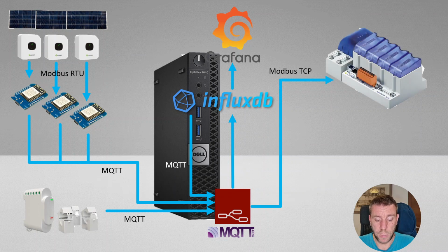And then once this is all in MQTT, in Node-RED, I need to pass this information to my PLC, which is a Saia PCD. In that, I created a couple of registers to hold all this information. So, how much I generated for each inverter, what is today's total consumption, so that's 4, and I have 3 more for the 3 phases, which you could see on the screen, and then 2 more registers for the 2 balances that you could see on the top of the screen. I just update these holding registers using Modbus TCP.